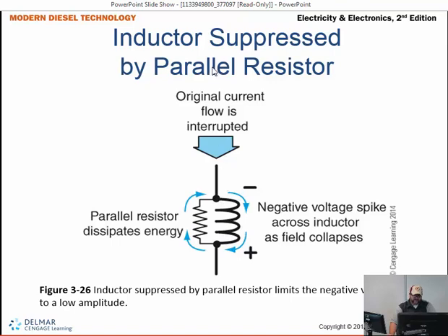We cannot have that because now it's going to want to feed back up here. So if this was our PCM, our powertrain control module, or a body controller, we're going to have problems that could damage that circuit. So we want to manage that, and one way to do that is to add a resistor in here with the electromagnet.